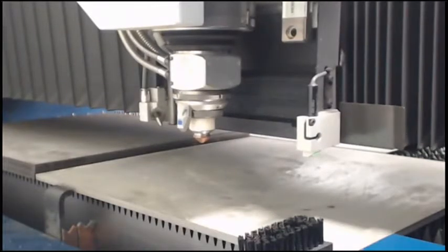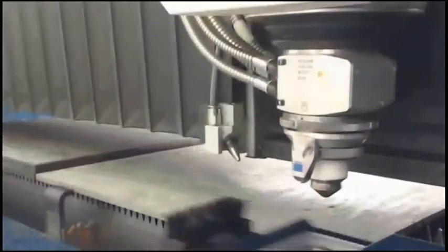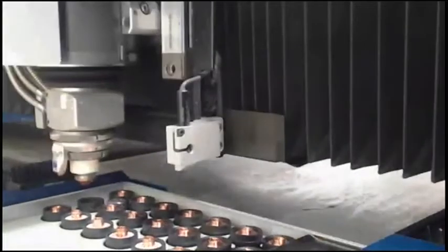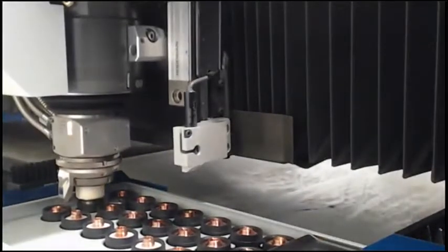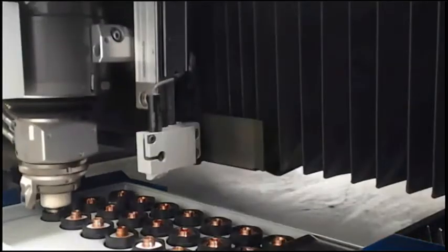So on to our next material. We have some 3/8 stainless in here. I'm gonna do a nitrogen cut on this. This is gonna be the Highspeed Eco, so that touchdown nozzle that Brett showed you guys before. This is going to be running at, I believe, 3 bar of nitrogen pressure. It's gonna be going 267 inches per minute using 12,000 watts. Again, doing our nozzle change here.